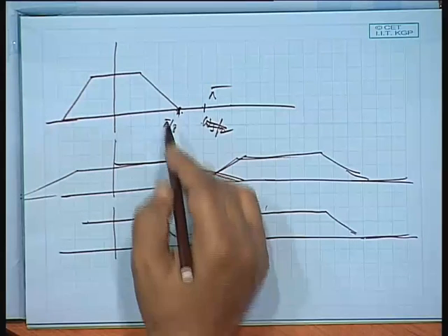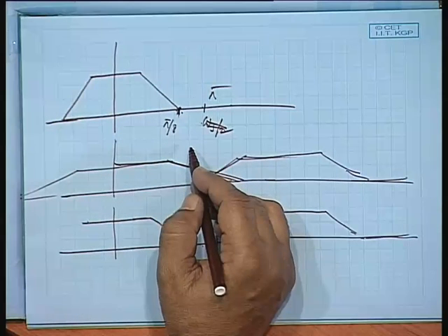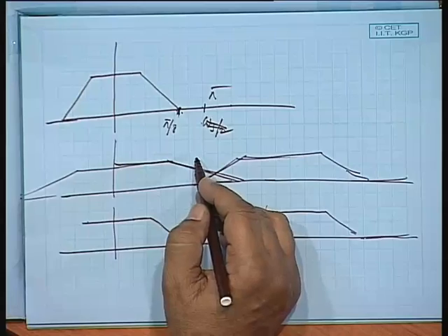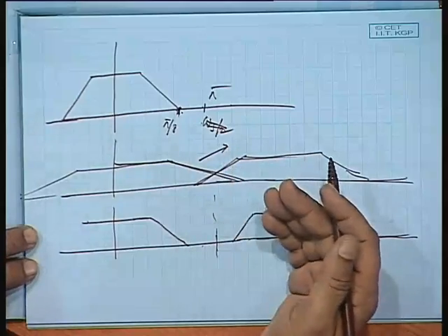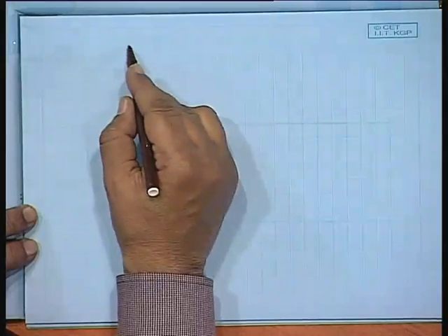So, we will see what should be the restriction on the rate at which we can downsample, and what are the filters required both for the upsampler and downsampler to see that the changed signal carries the original information. That means the frequency response does not get altered. I will lastly touch upon this point.